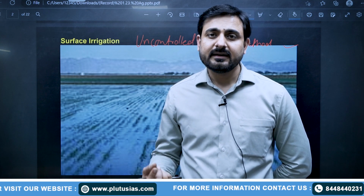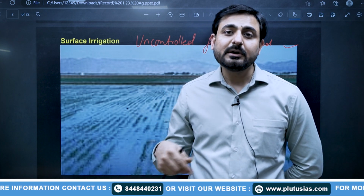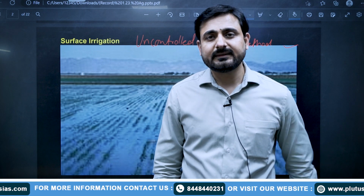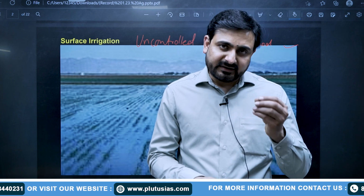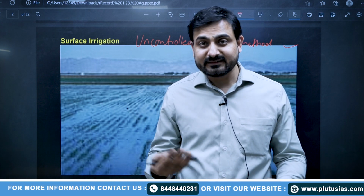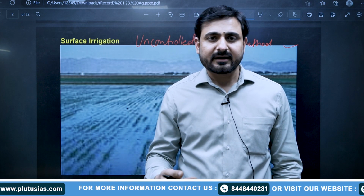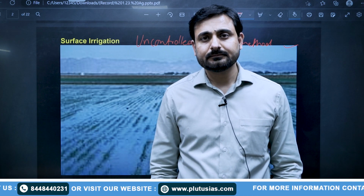In such a case, at certain places, the corners of your field may be overflooded. You can say there will be more percolation of water, meaning the moisture level and depth of irrigation will be more at such places, and at certain places the depth of irrigation moisture will be less. In such a condition, it will impact the overall growth of the crop.